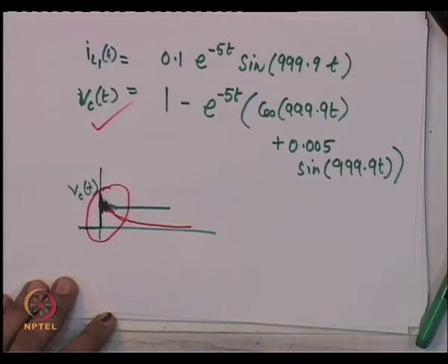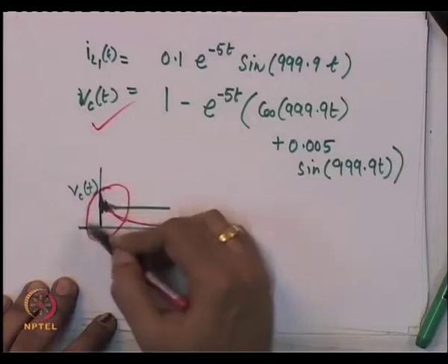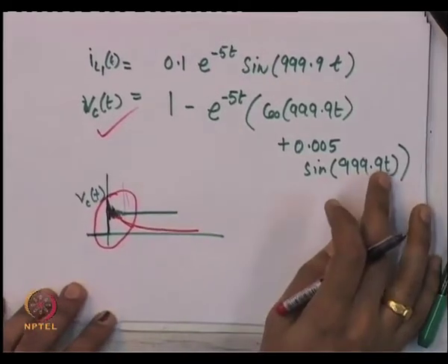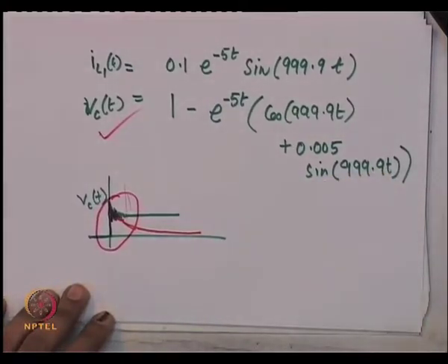So, if you are only interested in the initial behavior, in a very short time period, you can assume that the slow state, or the state associated with the slow variable, is just frozen at its pre-disturbance value. So, that is an important modeling point which you should appreciate.